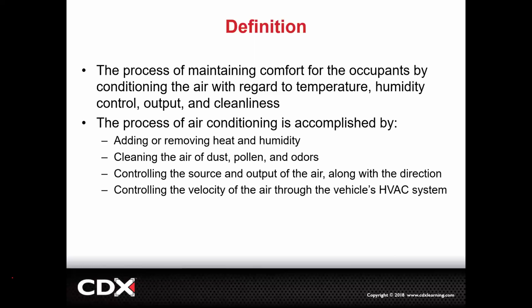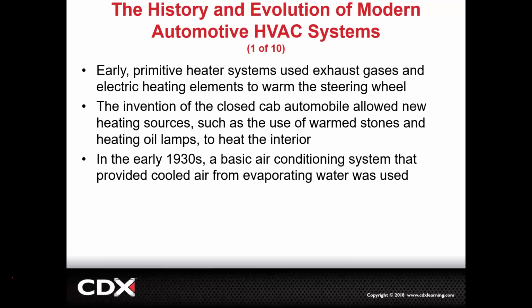We might have a control module, but that part of the system works with all these other parts of the system to do all those things that we want it to do. But when a car comes in and you turn it on the high speed and it gets no air, you don't have any business checking the heater core and checking the thermostat and checking the refrigerant level. If it's blowing no air, get down here to the blower motor and the associated circuit and components, right? So just giving you a little overview.